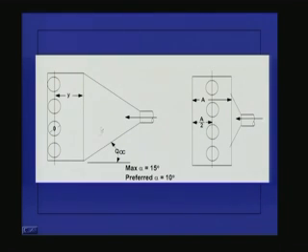So the sump design should be such that even when 1 or more pumps are operating, or let us say not all the pumps are operating, the flow structure here is conducive to obtain maximum efficiency. And there are limitations on what is the maximum angle you can take for this expansion here, and let us say preferred angle is 10 degrees.